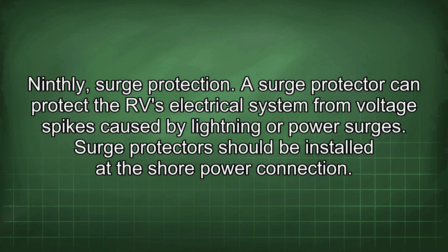Ninthly, surge protection. A surge protector can protect the RV electrical system from voltage spikes caused by lightning or power surges. Surge protectors should be installed at the shore power connection.